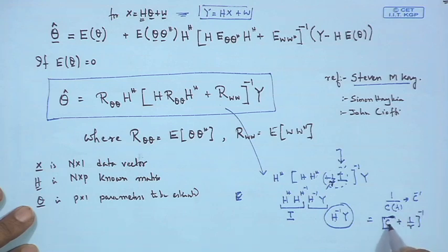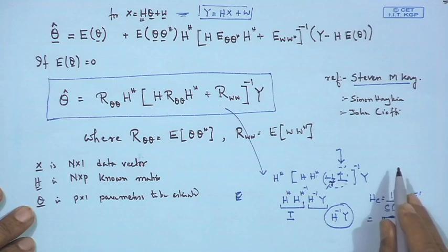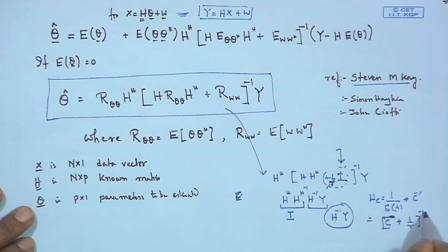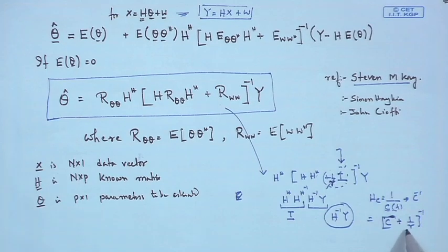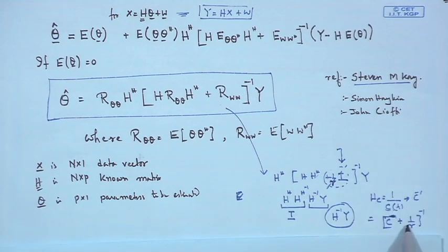That means, if C goes to 0, that means when C is very, very small, the H EQ is very large. So, when C is very small, it goes to 0, the inversion becomes very large. So, we are restricting it by this parameter, by this number over here. So, if C is very small, the inversion will not be very large, because it is restricted by the 1 upon SNR parameter. So, it restricts the noise enhancement, which was a typical problem in case of zero forcing equalizer.